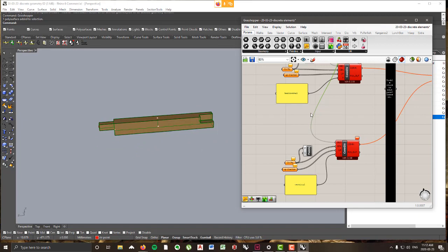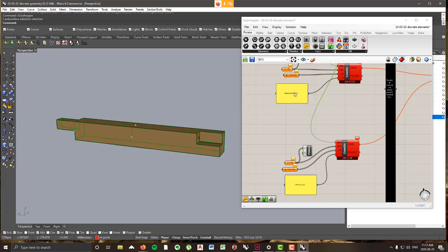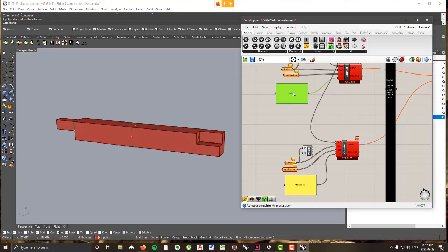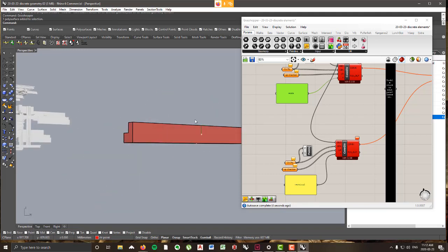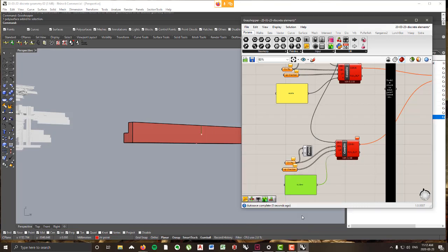And then I'm going to change my labeling for my connections, because this geometry is a little bit different. I'm going to say that these connections here and here, this mechanical lock, or this mechanical joint that we have there, I'm going to call it ends. So I'll call my first connection type ends. And then any connection made on the sides of this component, I'll just call sides. Click OK.